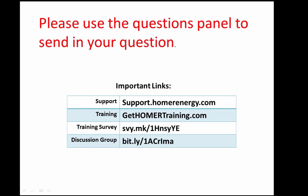Right. Wind data is so much more site-specific than solar data. So the NASA data will give you the seasonal profile. It'll give you some kind of average over an area, but especially if there's any complex topography, mountains or ridges or anything, it varies over very short distances. So you'd still want to do a sensitivity analysis, and if you're on the verge of making a significant investment, you probably want to actually put up an anemometer and measure it.